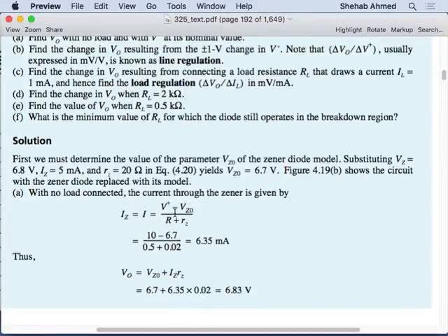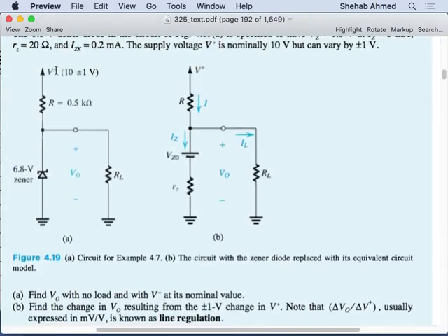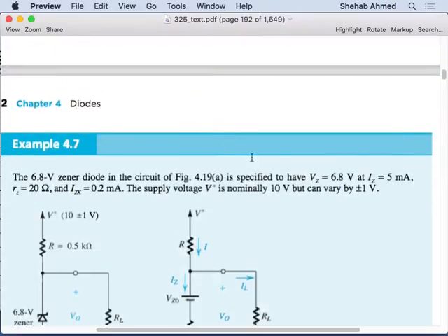So it's equal to what? The 10 volts, my VCC voltage, right? Minus what? Minus the Zener voltage, because again, open circuit now. I will have to assume something to start with. I will assume it's regulating at 6.8. It's a 6.8 volt Zener, it's open circuit. Right? I'm given these characteristics from my data sheet.